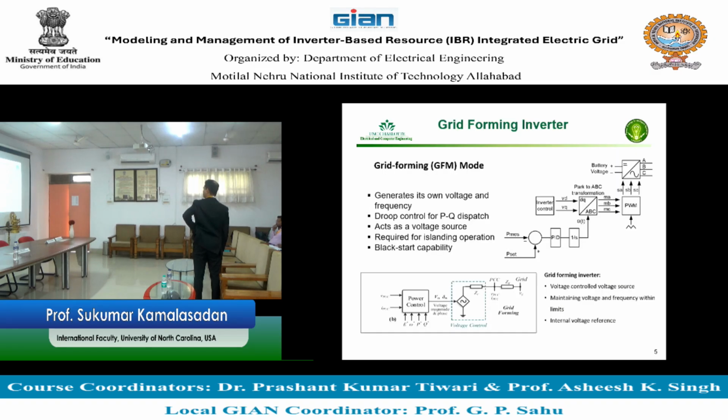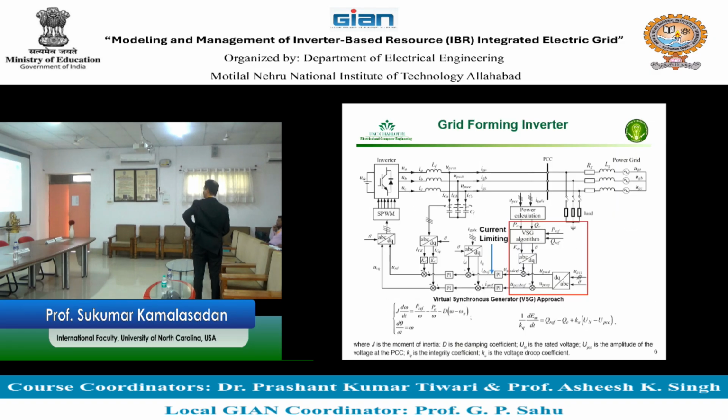So as opposed to the grid following mode of an inverter, for a grid forming mode of an inverter, you generate the angle. Okay, you understood, right? You generate the angle. You also need to generate the voltage, right? Because if the grid is gone, you don't have a voltage. Generate a voltage means what? You need to maintain the voltage, right? If there is nothing to maintain that voltage, nothing is connected, this voltage starts collapsing. So you have a reference and you maintain the voltage.